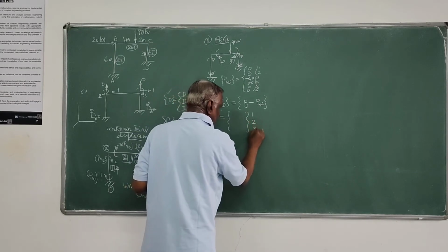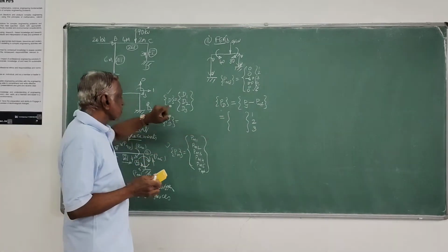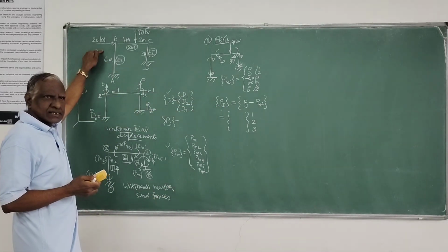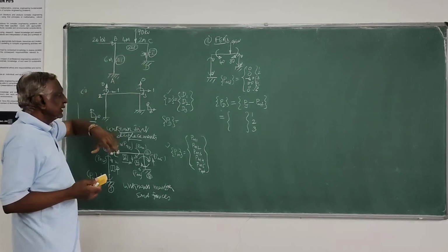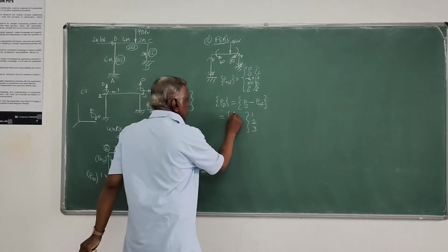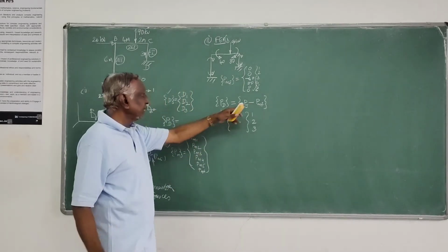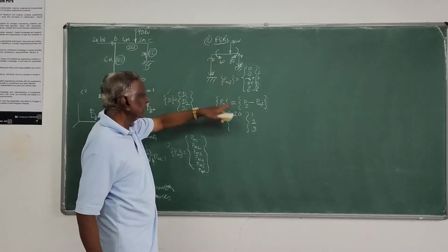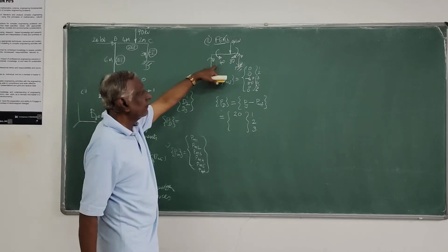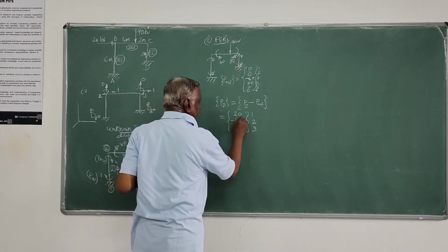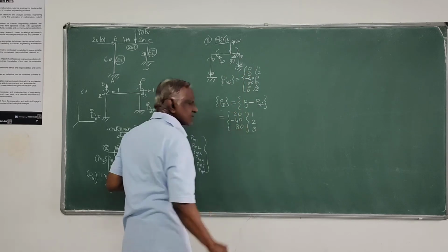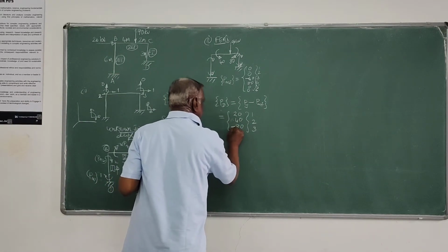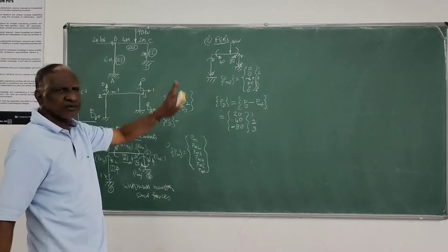It corresponds to the unknown joint displacement, corresponding to direction one. Pj is there. Now this joint load comes into the picture. 20 kilonewtons, it is in the direction of the coordinate axis chosen. So it is plus 20 minus PMF, which is 0. There is no fixed end action corresponding to that. Corresponding to 2, it is minus 40 because it is in the anti-clockwise direction. Corresponding to 3, it is plus 40 minus 80.